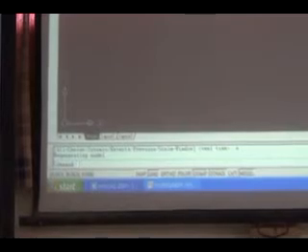Using commands, or nowadays we have icons. Suppose I want to draw a line. You see I have a line icon here. So I am clicking line. Suppose I want to draw a reference line first of all in your drawing. Say in the middle I am drawing a reference line. So wherever this is a start point, wherever you want to end, I can end it. You see, whatever angle I can draw it.